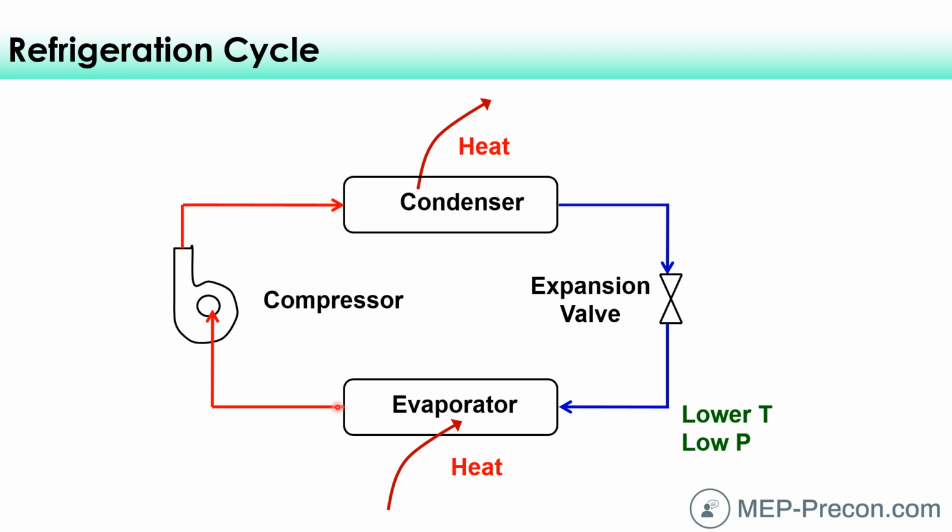And so now it leaves the evaporator as a complete gas. There's no more liquid, it's all evaporated, or boiled off, into a gas. And the temperature of this now is a little bit higher, still at a low pressure. We haven't done much to change the pressure. It's absorbed some heat, and so that heat results in a higher temperature. Now it might be, say, I don't know, 50 or 60 degrees or so, the refrigerant now. And now it comes into this compressor as a gas.